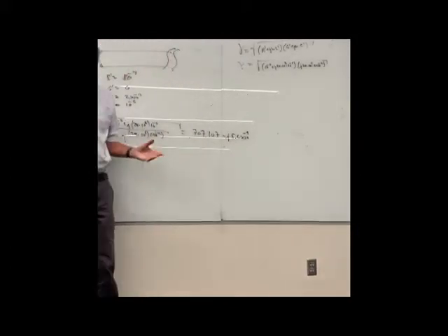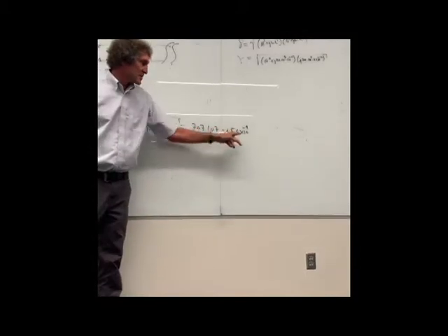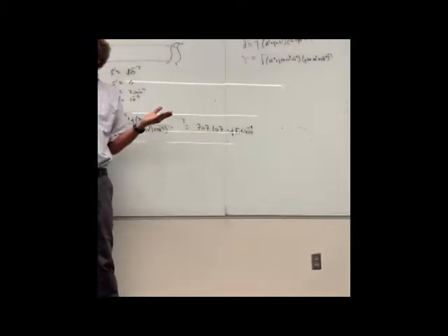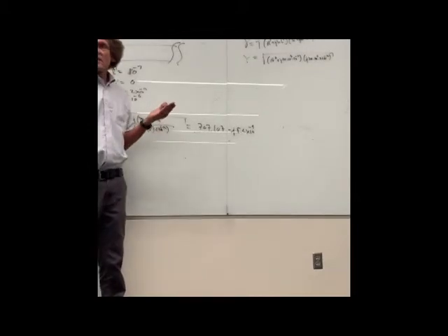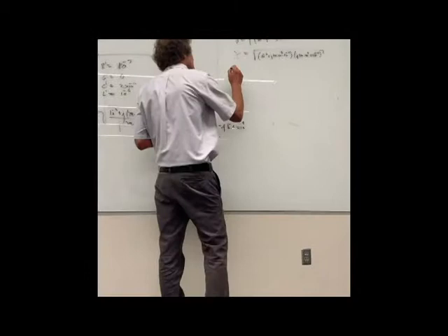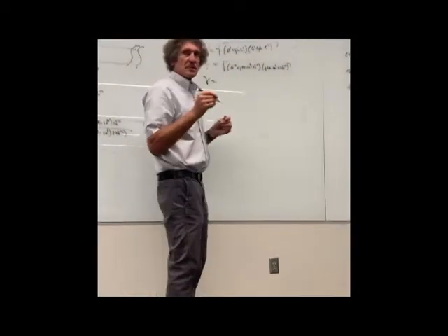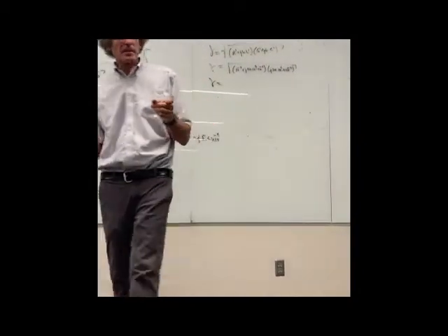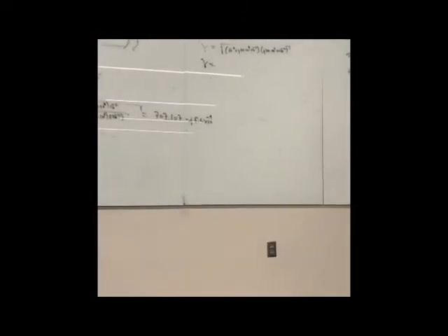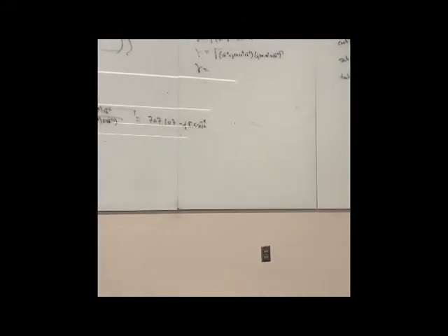Just for the basis of reason, this is about 0. All right, so you can say it's about 707 ohms right there for characteristic impedance. For gamma, what did you get for gamma? Propagation constant. Did you get that? I got 0.707 times 10 to the 9.